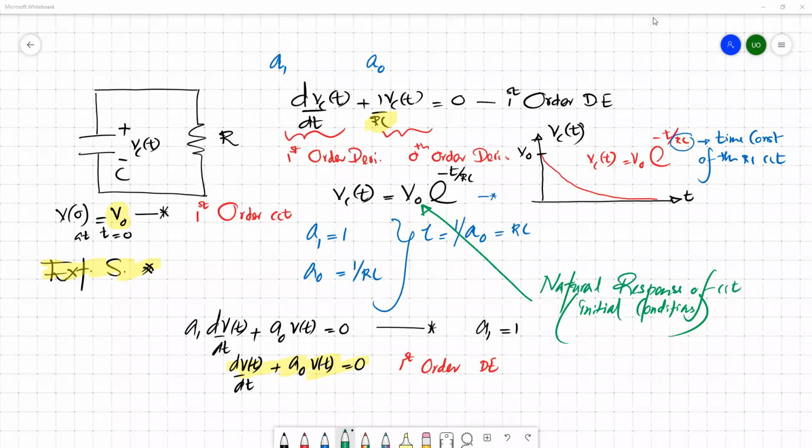For example, if you need to analyze V1, you will end up with two linear equations containing V1 and V2. You use one equation to obtain a value for V2 as a function of V1 and substitute it into the other one.